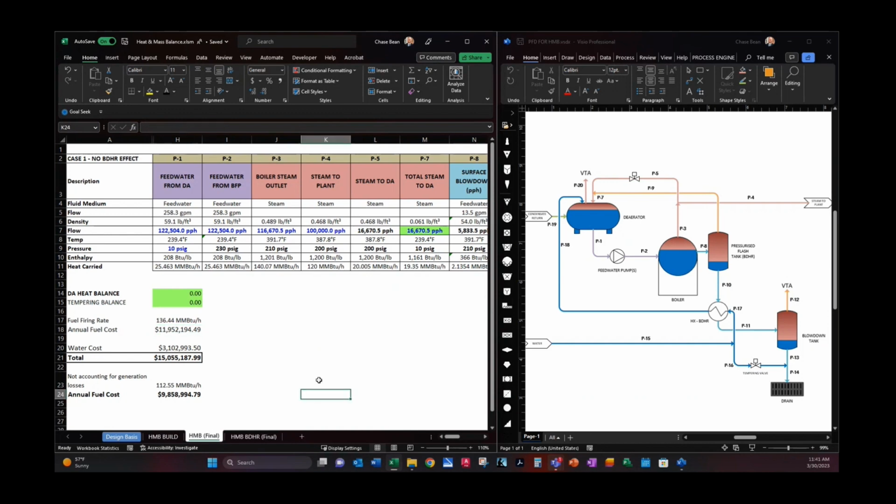And that's another thing that the heat and mass balance helps figure out. That will change based on condensate return, temperature, and the vent rate of your deaerator. So there's a lot of components here, and you're starting to see why it's necessary to do this whole balance. Anyway, we'll go on to the next tab where we have actually calculated this out.